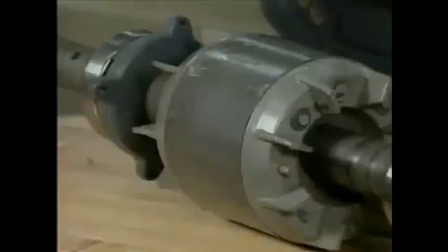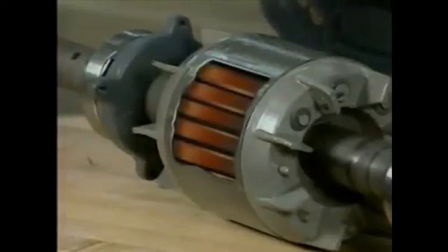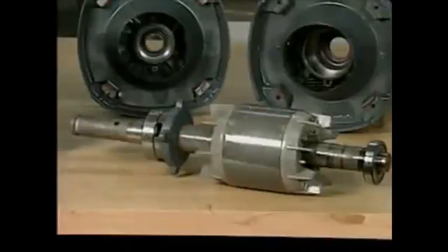The rotor is mounted on a shaft. This rotor is made of conducting bars that are shorted together by end rings. The rotor bars with their end rings are attached to a shaft so that the whole assembly can turn together. As the magnetic fields generated by the stator windings pass through the rotor, a voltage is induced in the rotor. The voltage creates current flow through the rotor, which creates another magnetic field. The interaction of the magnetic fields generated by the rotor and the stator windings produces motor action, which causes the rotor to turn.